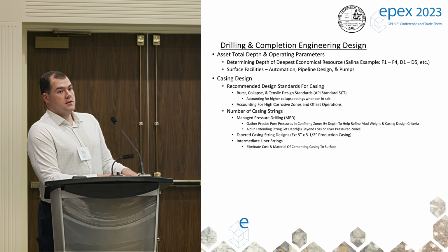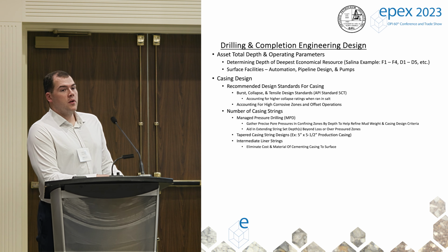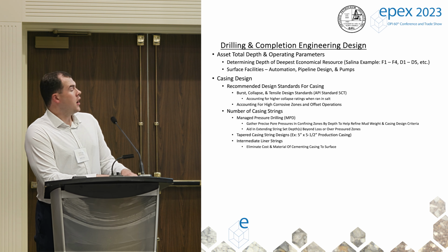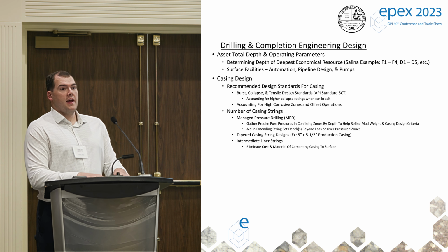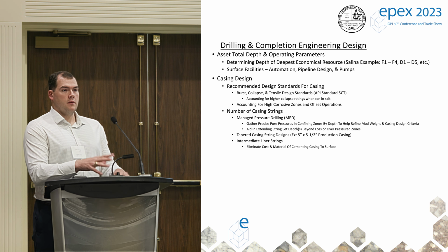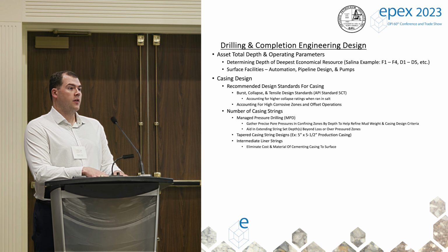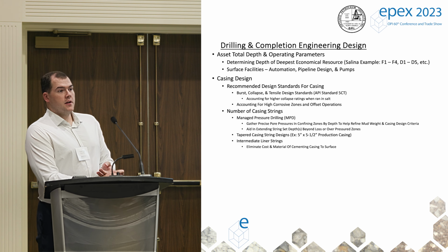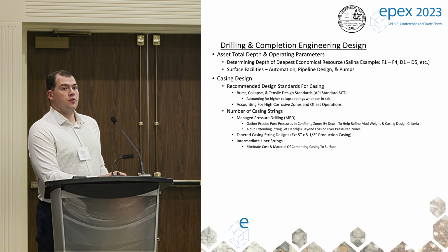Most of these facilities, oil and gas casing specs will overwhelmingly meet what y'all are requiring. But as you move into the higher operating pressures, you enable yourself, as far as casing design, to later flip this asset for gas storage. A lot of the solution mining guys are only worried about, hey, I only want to get my salt out now, my resource now for disposal. If you take the time and set it up front, welding your production casing string goes in. That's a simple thing you can do. It seems like a lot of money up front, but now you've enabled yourself to operate in gas storage applications, which greatly improves the upside if you ever need to flip it or have rental rates going on for firm storage.